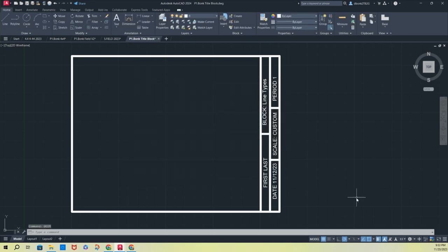All right, so the last thing with the settings is you have to make sure that the first four of these check marks are here. If not, go to the Object Snap menu, this down arrow, and make sure all these are selected. Otherwise, you're not going to get this done right.